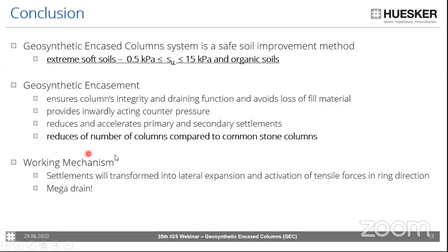And again, the encasement ensures the column's integrity and also the draining function, and avoids the loss of fill material. It provides an inwardly acting counterpressure, and it reduces and accelerates primary and secondary settlement. And we have also seen in the Hamburg case study that we even can reduce creep settlements. And compared to other